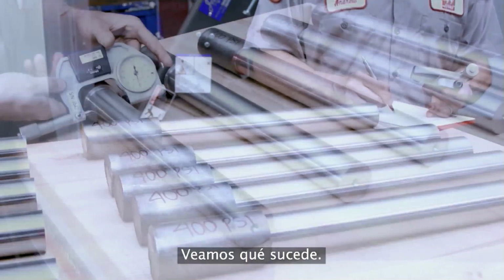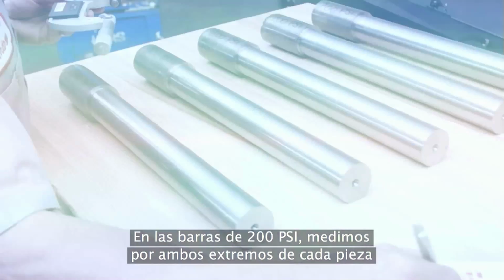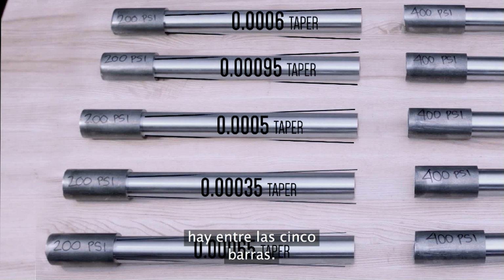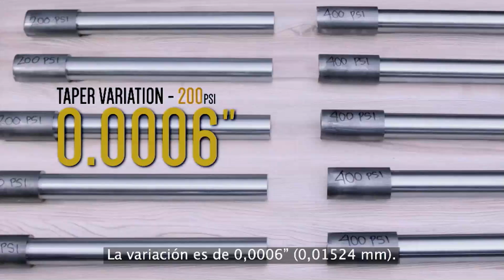Let's see. For the 200 psi shafts, we take measurements at both ends of each shaft to get a taper value. Then we compare these 5 values to find how much the taper varies for all 5 shafts. The taper varies by 6 tenths.